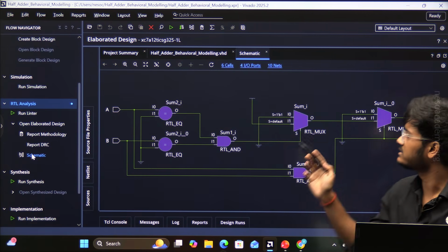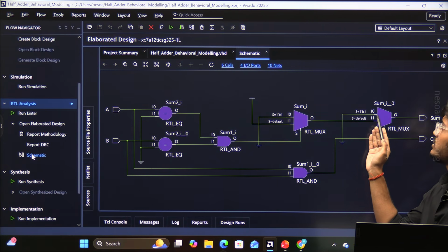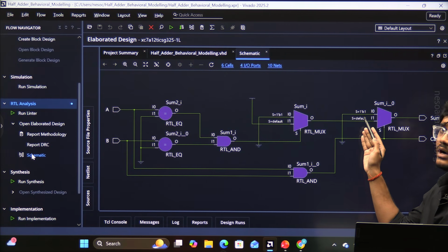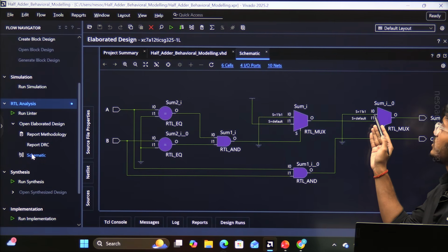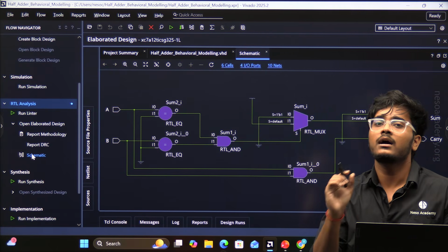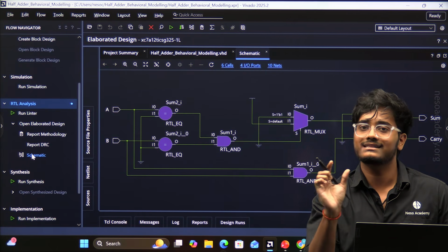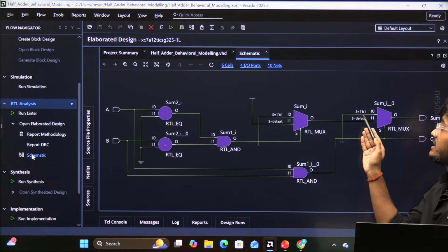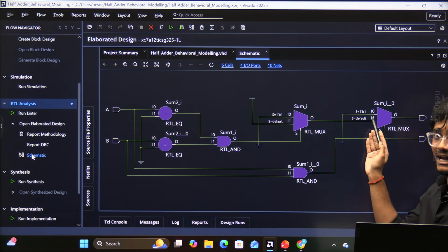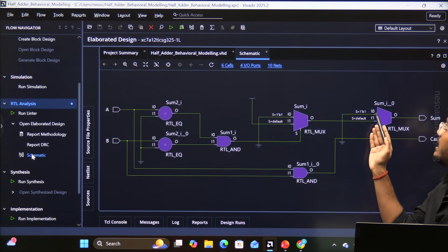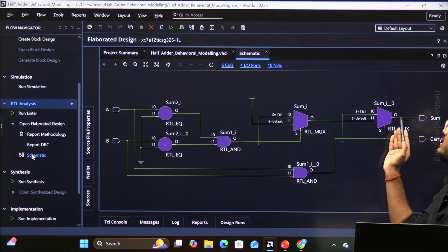And the same thing is written over here. On input line I0, we can clearly see S is equal to 1, B1, which means select input line I0 when S is equal to 1, which is of size B1. B1 means bit 1, the size of select line, which is 1 bit. So, when select line is equal to 1, then select input I0. Now here, we have S is equal to 1, which means input I0 will be connected to the output.